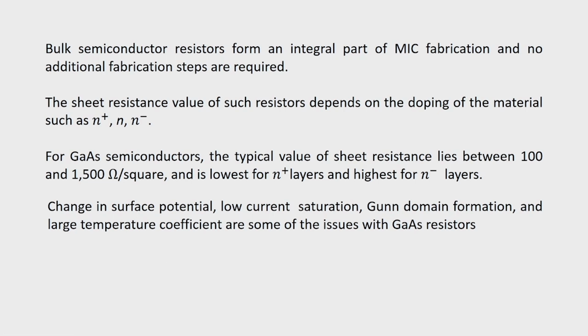Now, gallium arsenide resistors have some issues, and these are change of surface potential, low current saturation, Gunn domain formation and large temperature coefficient.